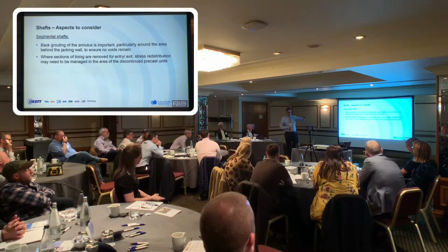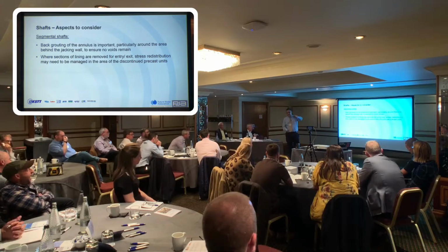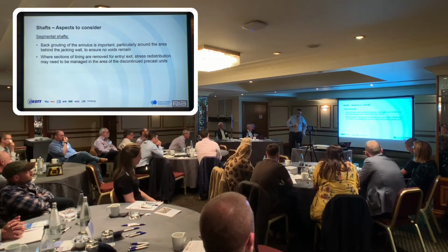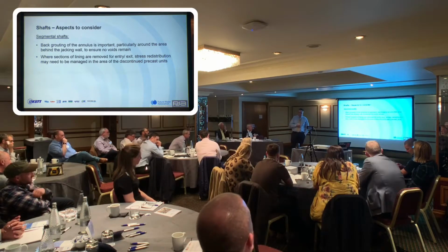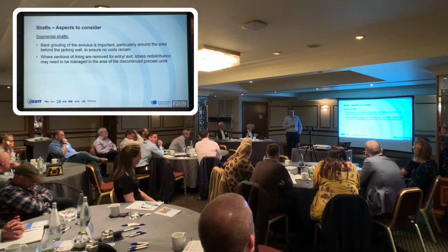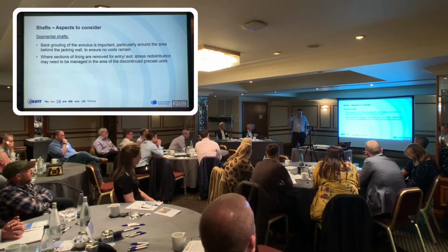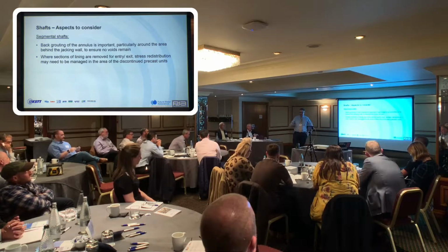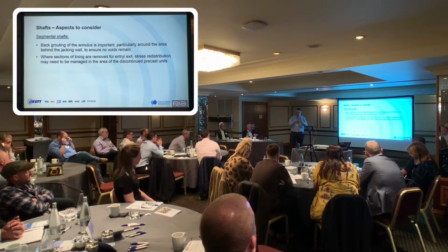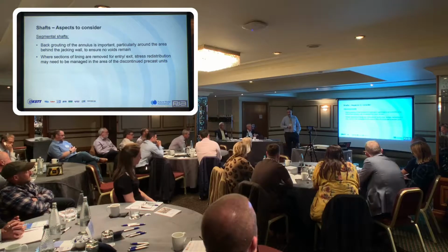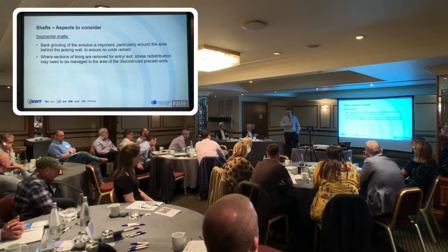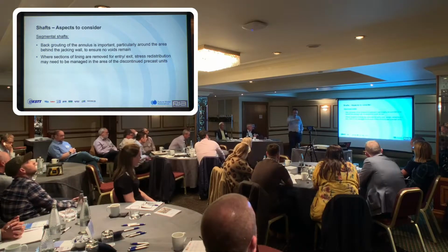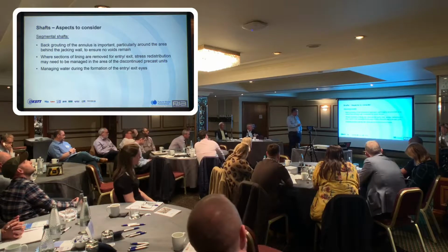So in essence, if you've got a metre deep unit and you take a hole out of it, as the load comes round, it will want to flow around that opening. And if you haven't got enough of the ring left to carry the load in terms of the area of the concrete, then typically you need to do something to reinforce that. It could be channels, parallel flange channels that are dialled in so that the force is captured and transferred through the dowels into those sections. Or very often it's driven down a pattern of studs, and then it's a reinforced concrete head wall, so as the load goes around, it's transferred past the opening.